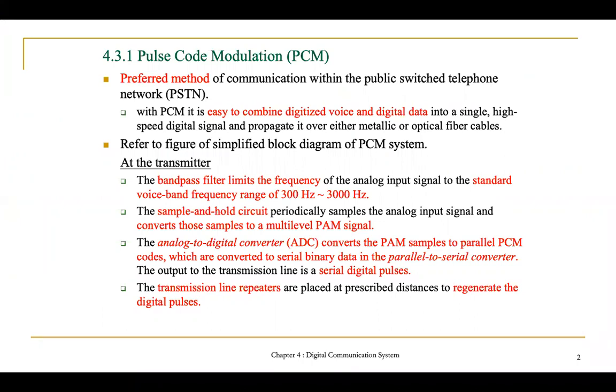So now I will focus on pulse code modulation, or PCM. PCM is the preferred method of communication within the public switched telephone network. Okay, why is it the preferred method? Because it's easy to combine digital voice and also digital data into a single high-speed digital signal and propagate it over either metallic or optical fiber cable.